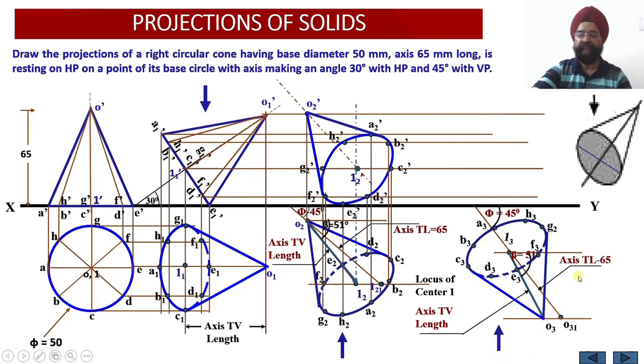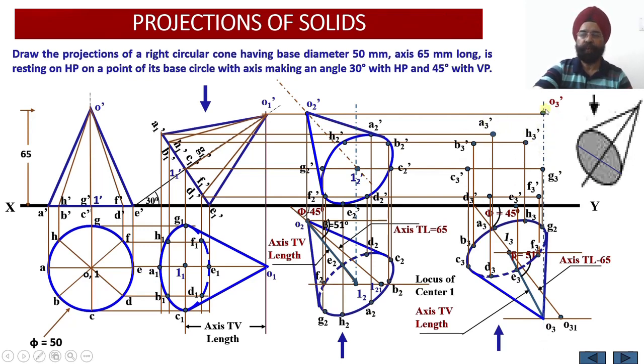So let us draw the projection. So once again, 10 points are lying onto this particular plan projection. So all 10 points will be drawn upwards. Just see one by one the corresponding intersection points. Just like in this case, they have been evaluated. So I am showing you all these points one by one. So having located all these points, now we have to see, this is the ellipse. Please see, this is the ellipse. From here one tangent will go here, from here one tangent will go here.